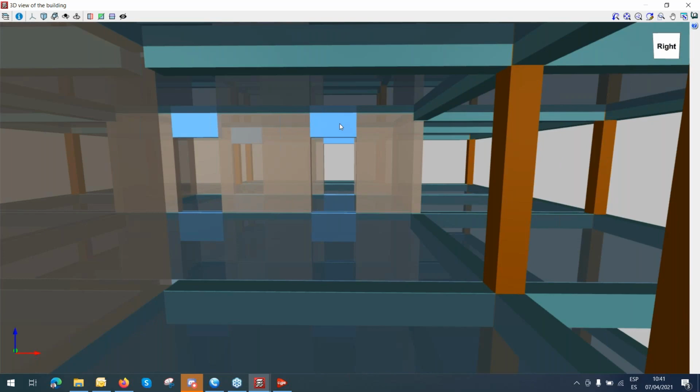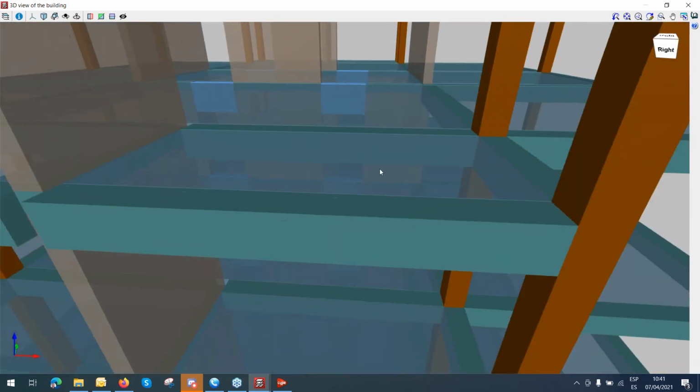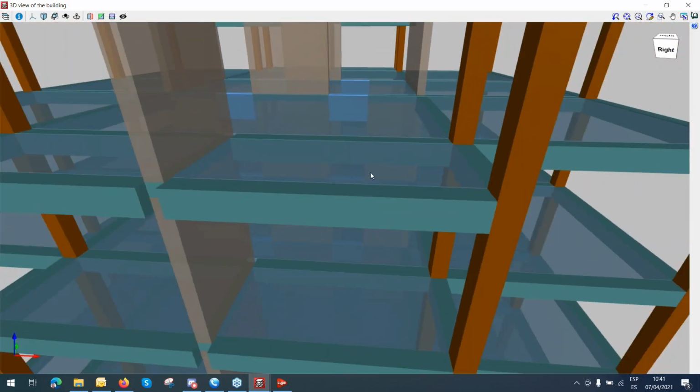That beam is called a coupling beam. That coupling beam is also calculated with the software Shear Wall Design, and gives you the reinforcements. They give you the requirements to fulfill the code that we are using. Right now, we can use the ACI code and also Eurocodes and the Mexican code as well. And we are going forward.